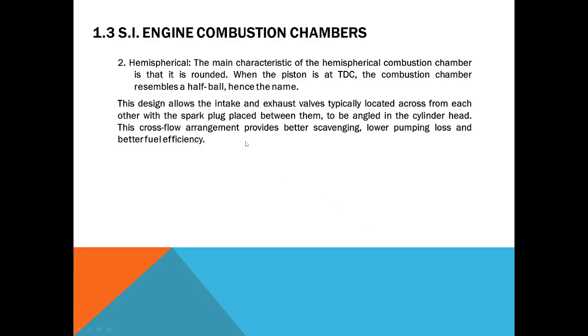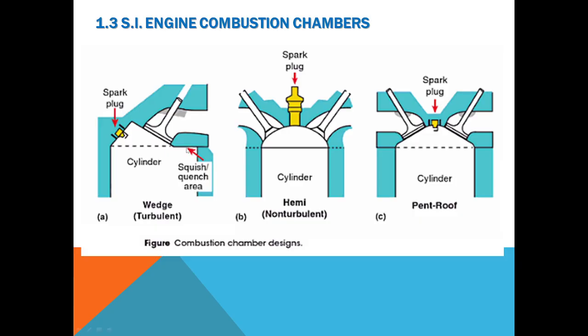Now, in the case of the hemispherical combustion chamber, it has a rounded, hemispherical shape. So when the piston is at top dead center, the combustion chamber resembles a half ball. Hence the name hemispherical. This design allows the intake and exhaust valves, typically located across from each other, with the spark plug placed between them, to be angled in the cylinder head. This cross-flow arrangement provides better scavenging, lower pumping loss, and better fuel efficiency.